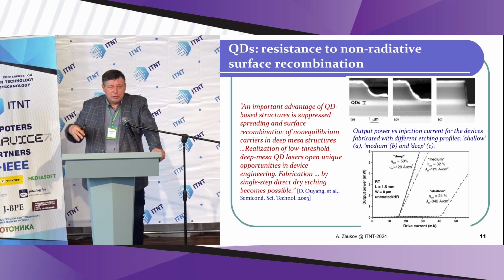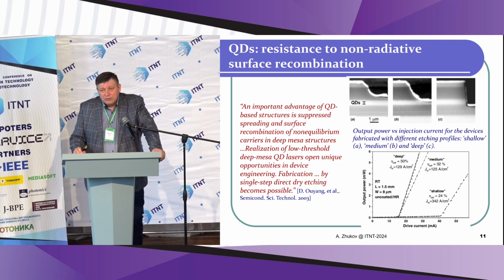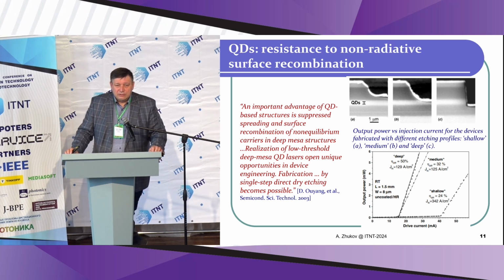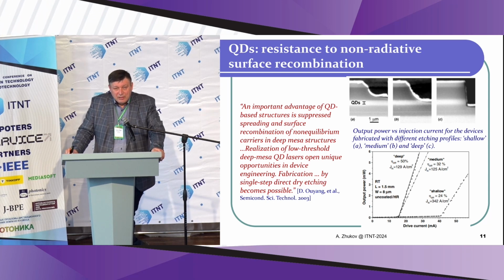And all these traps act as deep levels, which lead to non-radiative recombination, the same as the deep levels in bulk materials.